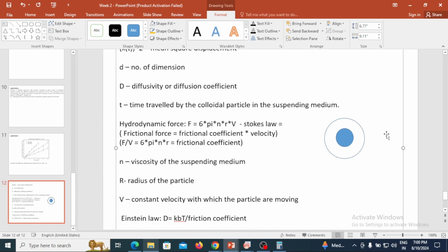Depending upon the charge of your sample, the positive particles will get attracted to the negatively charged gold surface, and the negatively charged particles will get attracted to the positively charged one. If opposite charges are present in the liquid, they will move towards either side of the gold electrodes, and depending upon the velocity of the moving particles, we will be able to calculate the surface charge potential, and from that we can calculate the surface charge density.